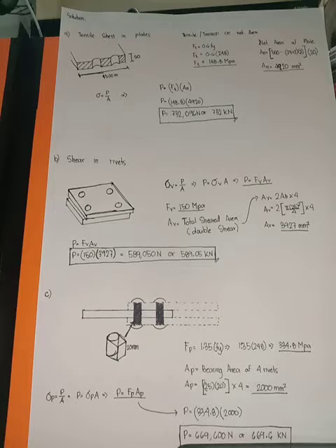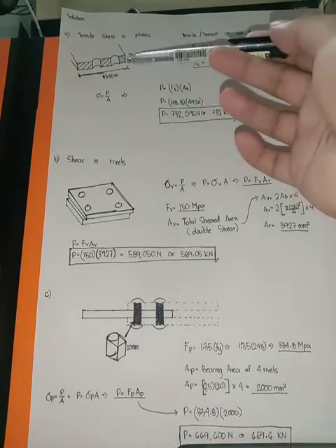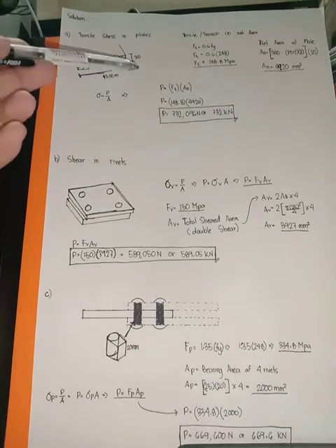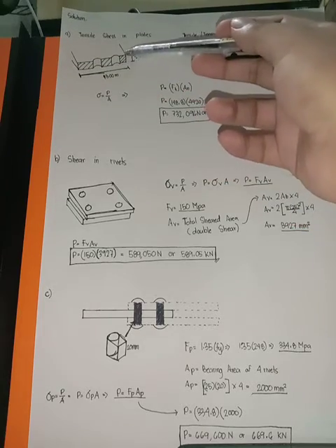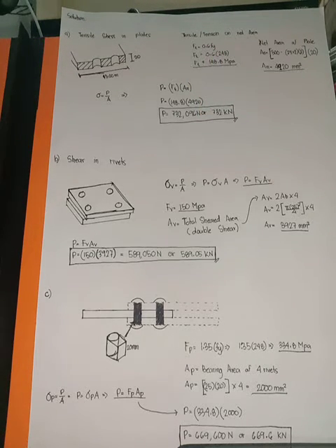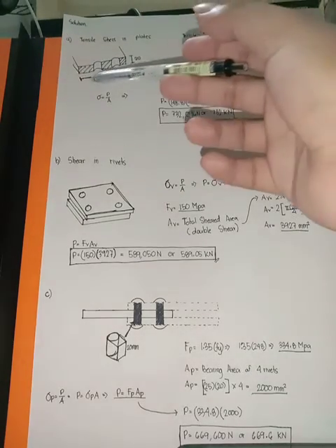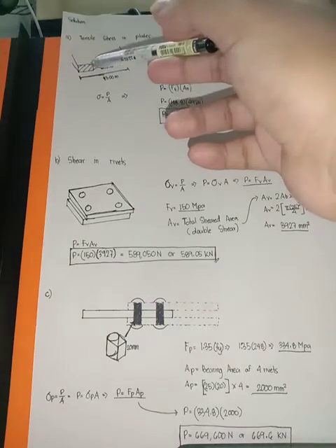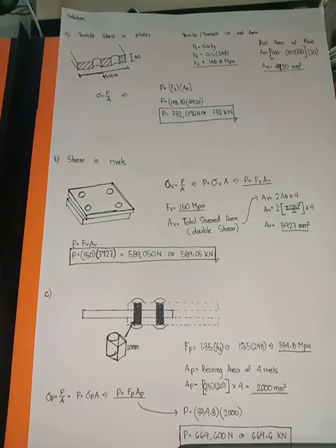Then the net area of the plate, so let us recall the area of our plate that experiences tension. This area is the base, and then the length, or the width. There are two areas here that do not undergo tension, so we subtract them. So 300 here is subtracted by this area. This area is 25 plus 2, because the diameter of the hole is 2 mm larger than the diameter of the rivets. Let us recall the problem.